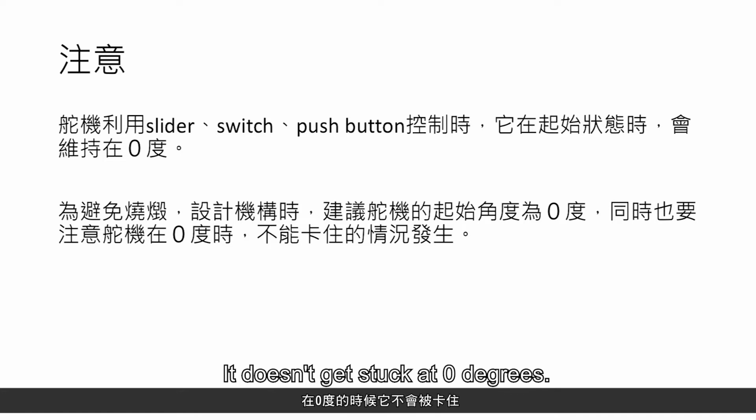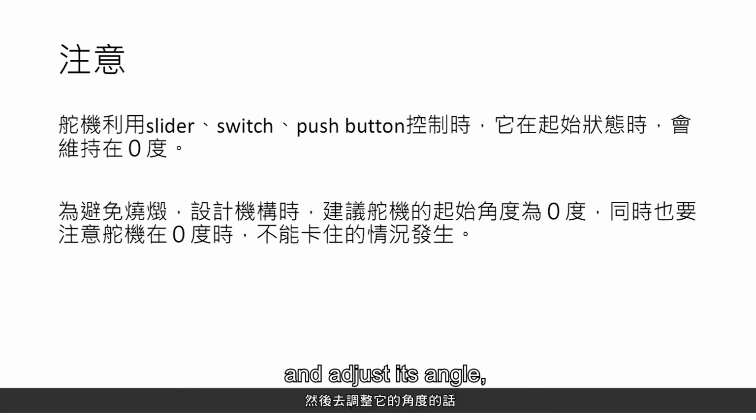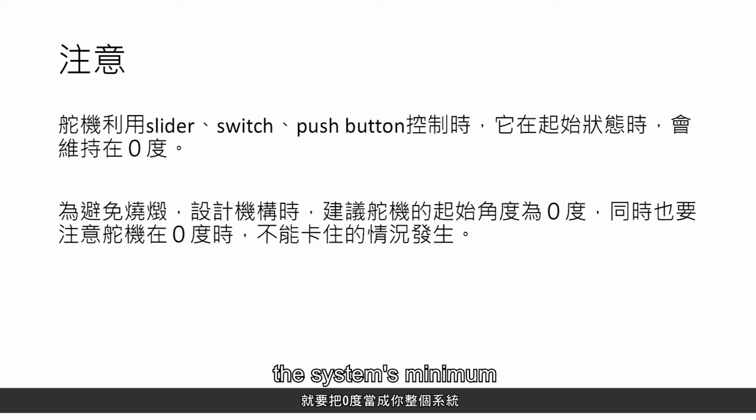It doesn't get stuck at 0 degrees. Otherwise, if it activates before you have time to log on into the system and adjust its angle, the current will continuously increase at this point and cause burnout. Therefore, it is suggested that you should set 0 degrees as the system's minimum initial angle so that it will be safer.